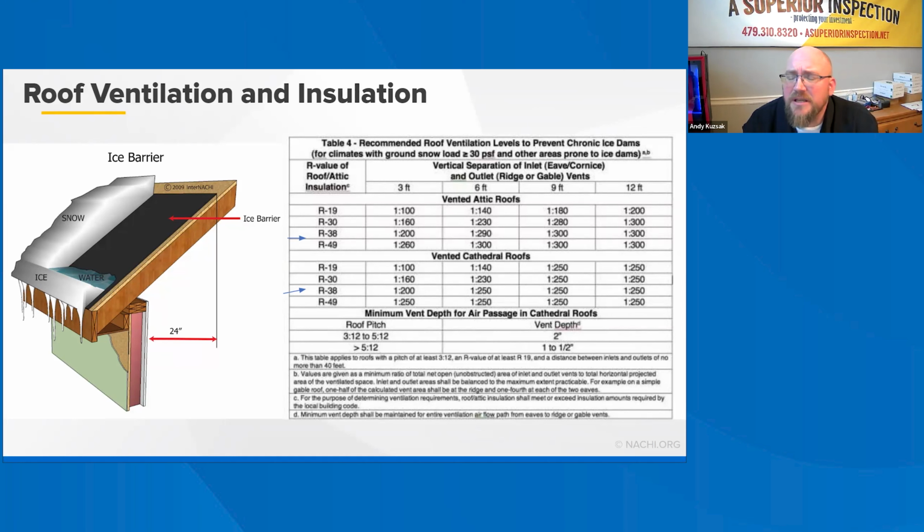Before we get into ice dams, I have a great example of what can happen with the lack of ventilation. So again, in my area, we are a hot, humid climate. And so because water vapor diffuses generally through our ceilings and then goes into the attic and then gets taken out of the roof by the airflow from the soffit vents up to the high roof ventilation. So that's our typical configuration here.